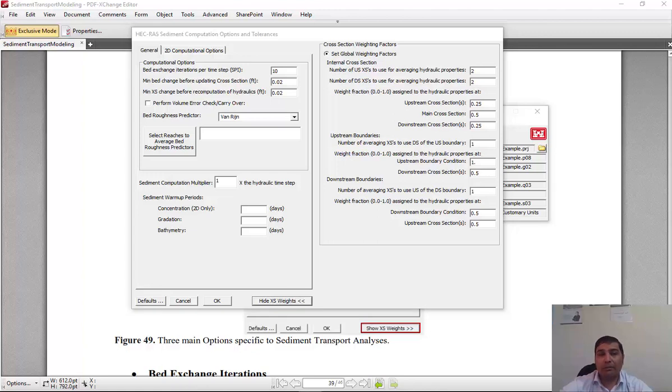Cross-sections are a bathymetric sample of the river form over a particular reach. Depending on their location, they can approximate the channel form and transport capacity well or poorly. Small hydrodynamic differences between cross-sections can cause local deposition and erosion in an equilibrium sediment transport model. Sediment scoured from one cross-section is often deposited in the next cross-section.